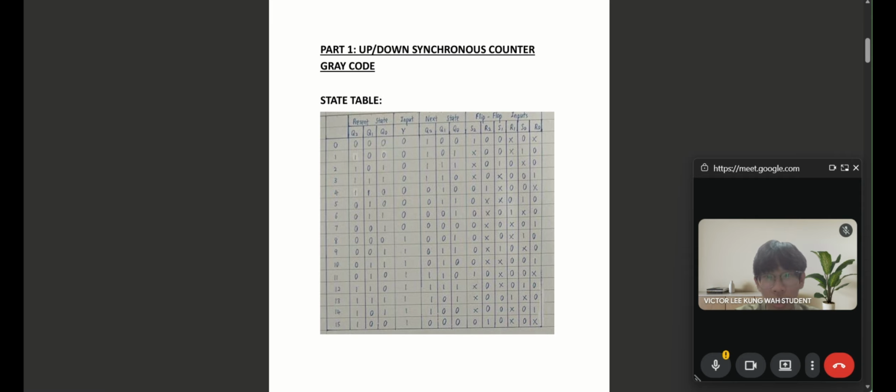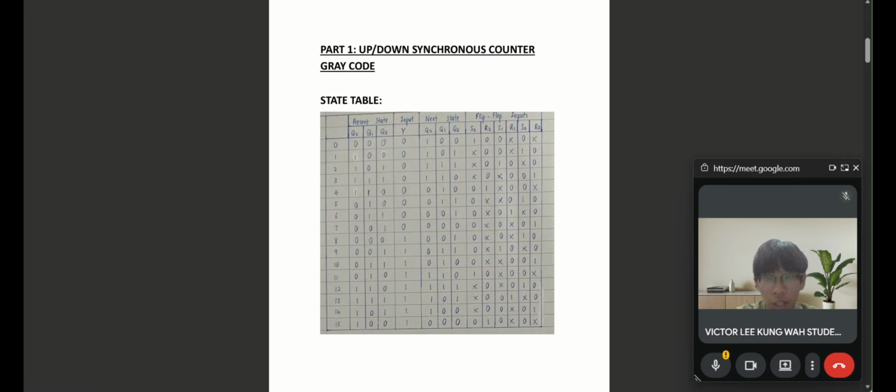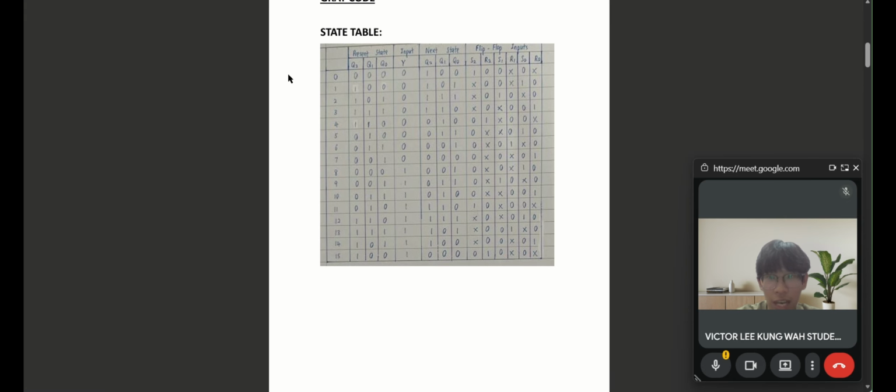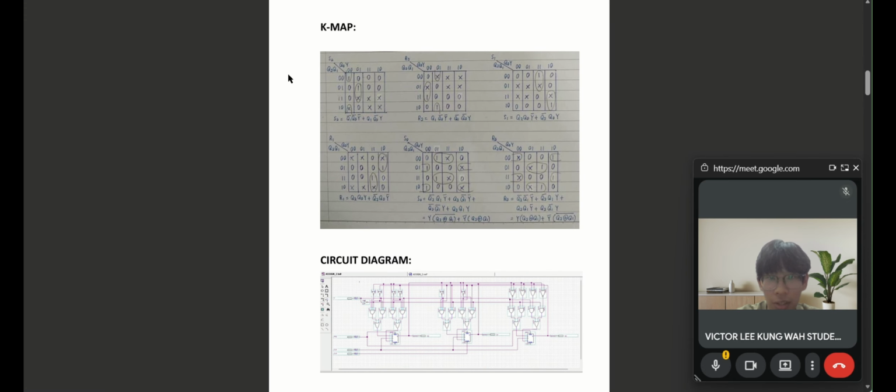For question 1, the question is a synchronous counter for a 3-bit gray code number using SR flip-flop. Firstly, we design the truth table following the diagram from the question. Secondly, we finish the SR truth table following the SR flip-flop formula with present state and next state 3-bit binary number. From the K-map, we take the SR result from the truth table for each column. For example, the S2 equation follows the similar characteristic from these two circles to form the